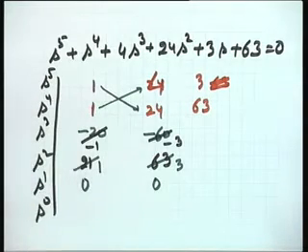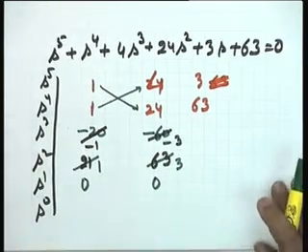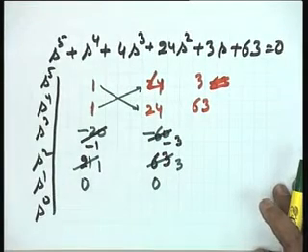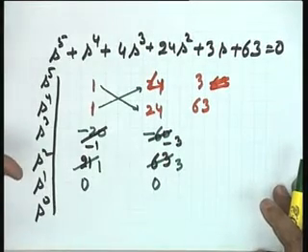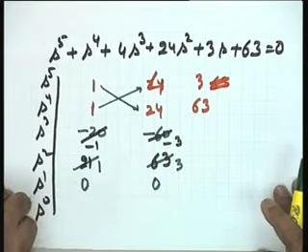So, actually in this particular case, when a complete row turns out to be a 0 row, note this point very carefully: this is an indicator, and this is the only indicator, that when a complete row turns out to be an all 0 row, there is a possibility of roots on the j omega axis. Not necessarily the last row, any row in the Routh array.